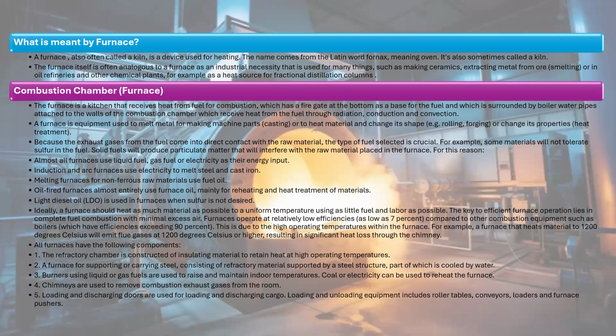The type of fuel selection is crucial. For example, some materials will not tolerate sulfur in the fuel. Solid fuels will produce particulate matter that will interfere with the raw material in the furnace. For these reasons, almost all furnaces use liquid fuel, gas fuel, or electricity as their energy input.